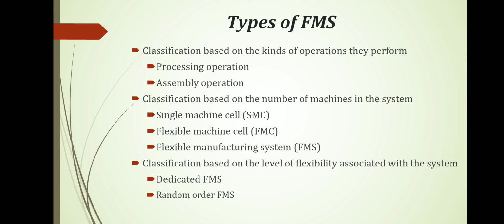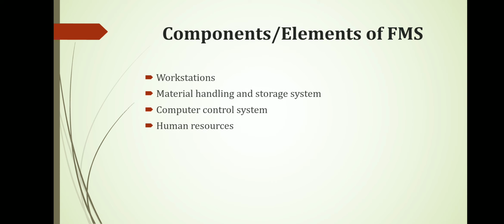Based on the level of flexibility, we can define dedicated FMS and random order FMS. Dedicated FMS means that for a particular design, for a particular product only, we make the system. That is dedicated FMS. Then random order means a different variety of products we are able to make.